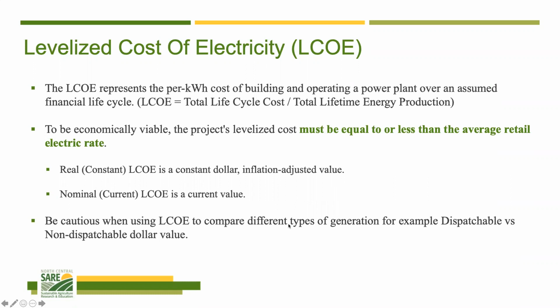What we do with that then is look at that output, that cost per kilowatt hour, and compare it to other options. So what am I paying my utility for a unit of energy versus what this system could produce it for? Recognizing that there is additional value from your utility because they can provide it when the sun's not shining, you kind of have to take that with a grain of salt. But it helps you recognize that if you're paying 8, 9, 10 cents and your levelized cost of energy is 18, okay, that's probably a pretty tough investment.